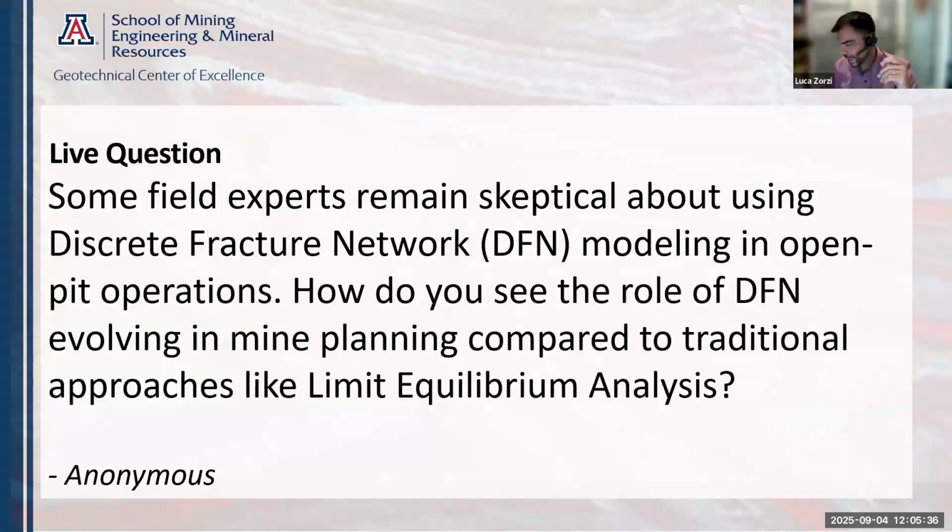I'm not a geotechnical engineer, but when I see a lot of limit equilibrium analysis used for open pit design in hard rock, my mind blows up a little bit, because we are assuming a lot more continuity in structures and in the system than actually exists in reality. And we go down the path of creating this weird formula to calculate rock bridges, to understand continuity of things, and then we do all of this beautiful math, and then we throw it into a software that considers everything continuous.